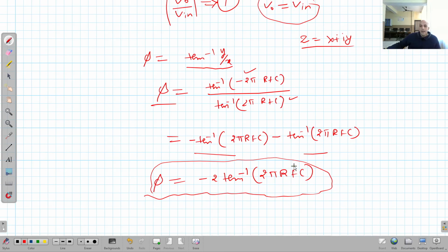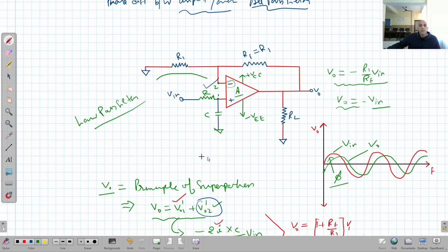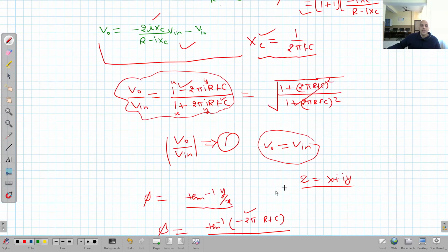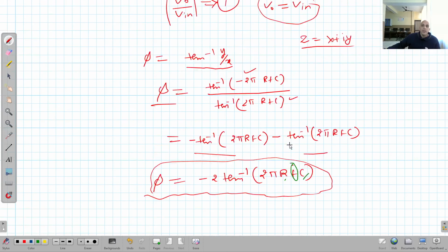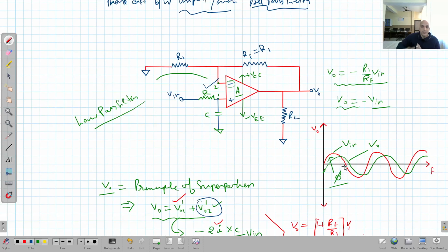And you can see here that it is frequency dependent. It depends upon the frequency, and upon the value of capacitance and resistance, right? But the main thing is resistance and capacitance are fixed in the circuit, clear, but the frequency of the signals applied at the input can change. Even in the input signal there can be different frequencies. So in that case the phase angle will be induced for all the frequencies depending upon their value. So we will have a phase shift for the different frequencies.